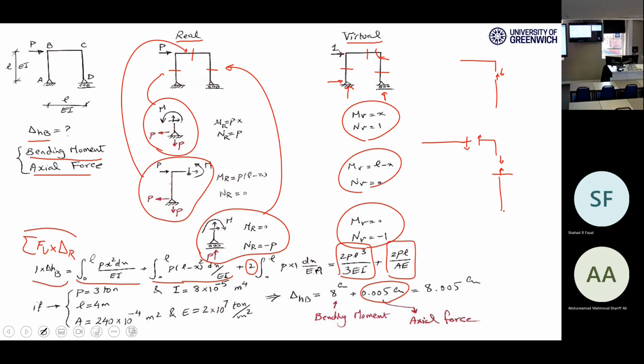You can never say axial force is negligible or shear force is negligible. If you neglect shear forces, you're affecting the equilibrium equation, so the equilibrium equation will not be satisfied. All the forces are there, but the contribution of some of them, which are usually axial force or shear force, into the deformation calculation is negligible. These are two different statements.